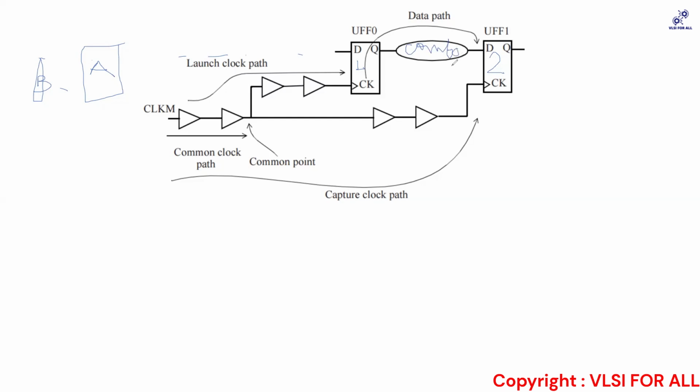It is not called a standard logic path or something, so understand why it is called a combo logic path. As I stated, the major bifurcation you can make between standard cells is to place them in two major units: either combinational units or sequential units. All the cells present in this circular box are always combinational cells: your AND, OR, NOT, MUX, AOI cells, OAI cells.